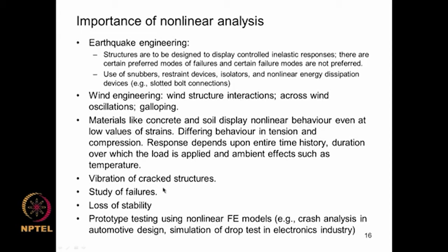A linear system in principle can never fail, it can withstand infinite stresses. There could be problems of loss of stability, this we have discussed, like buckling and snap through and so forth. In many modern applications, prototype testing using nonlinear FE models has become popular. For example, crash analysis in automotive design, simulation of drop test in the electronic industry, etc. Instead of performing costly experimental studies, cheaper finite element simulations are being used.